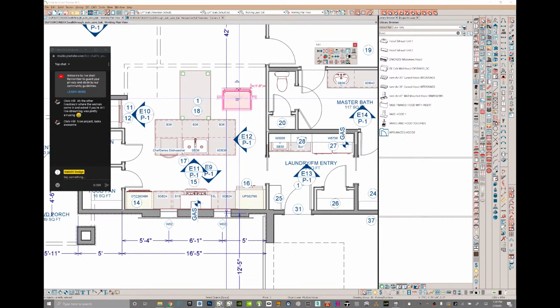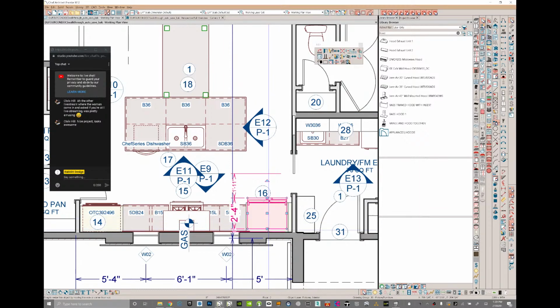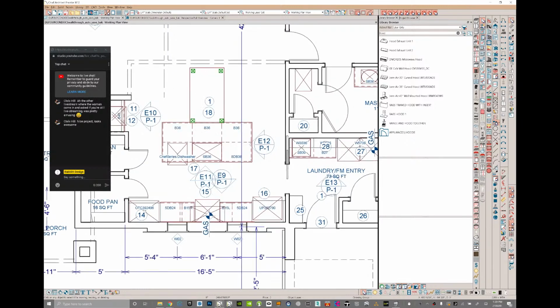So I'm hoping by showing people these drafting sessions that you're just picking up maybe some tools, and also letting you know that I goof up too quite a bit. I've got selection mode contained right now, which is why I'm able to just select whatever I want instead of everything that's intersected. So intersected selection mode is kind of a pain in the butt. But the contain mode is nice because you can kind of pick things as you need them.